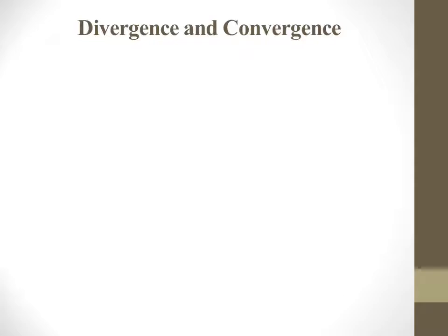The transition becomes active if all the steps preceding it are active. It means steps connected to it by vertical lines. If the transition condition is met, the next step becomes active.